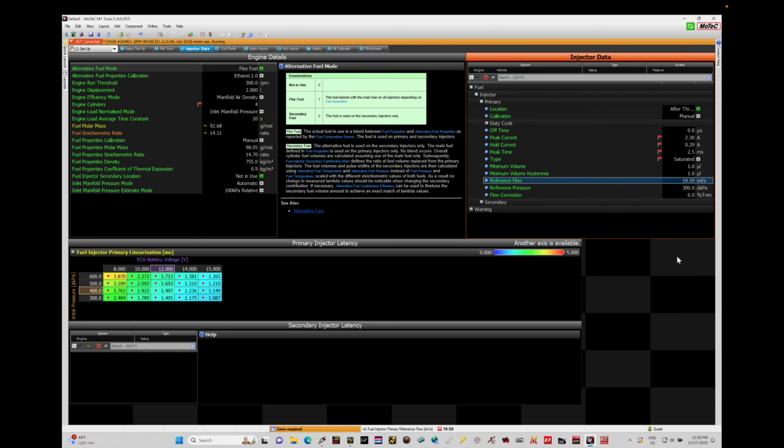And that's important because as we vary the fuel pressure, the actual injector flow will vary, and then Motec can calculate that and figure that out really quickly. So knowing what an injector is rated at in terms of flow and at what pressure is important information to program. Now, how do we turn the reference flow into a base injector pulse width, or the baseline of where we want to actually open and close that injector?